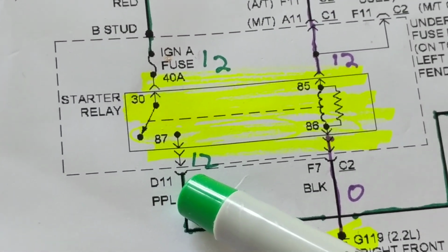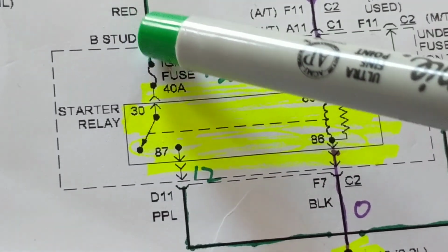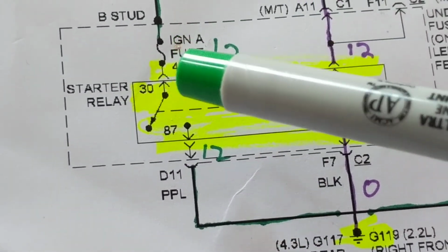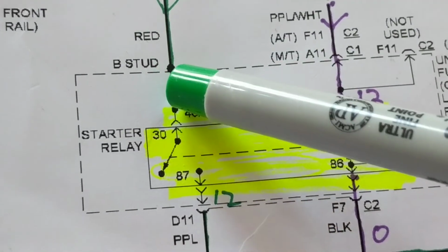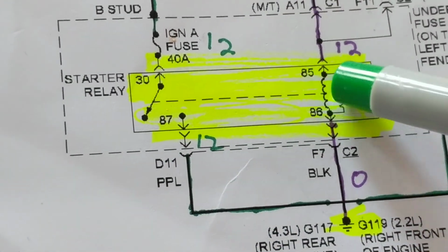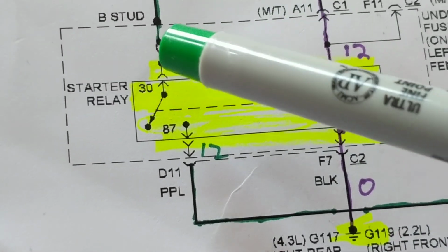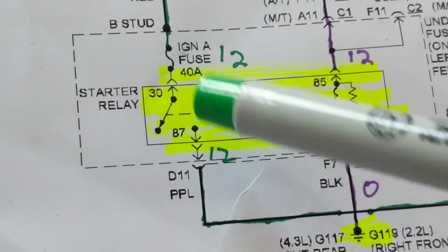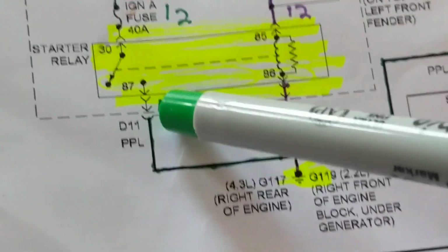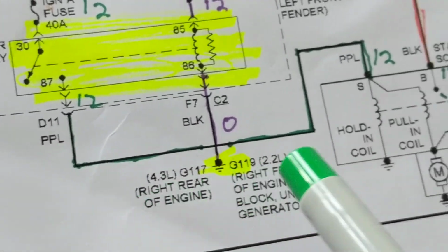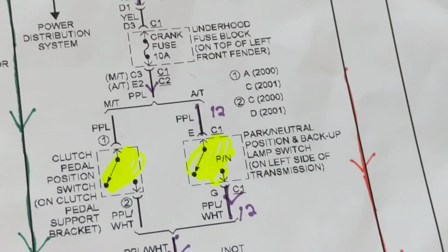That's what we want. So in other words, current goes here, and there's a connector here. There's a connector here. It's going through this red wire, coming out the purple wire, because this was activated. If this is not activated, this will be open. No current can flow. I'll have 12 volts here, and I'll have 0 volts here. So that's part of it, going to the starter motor.